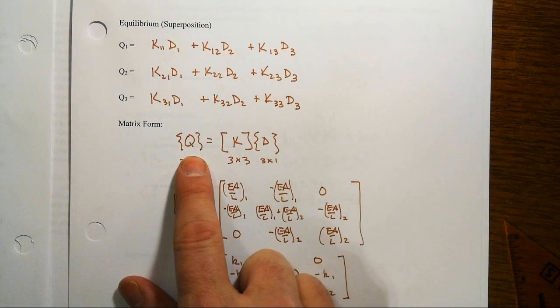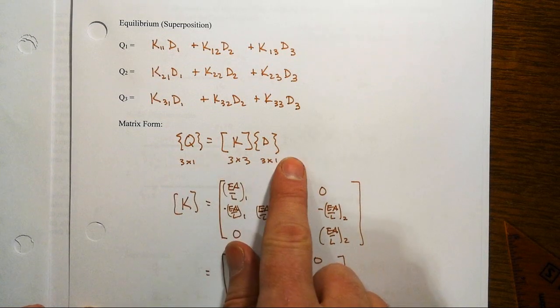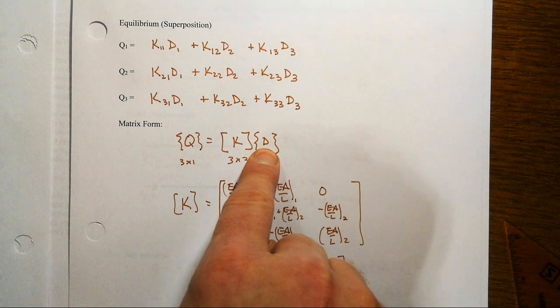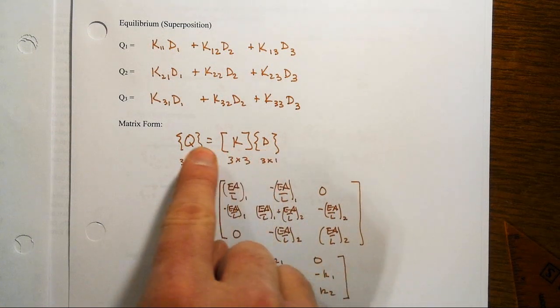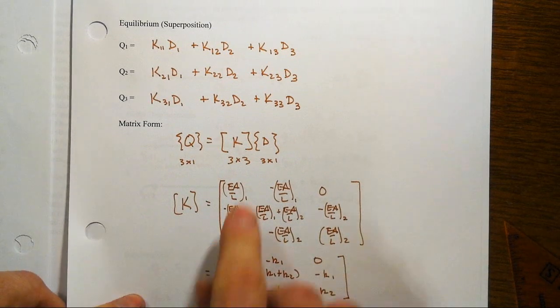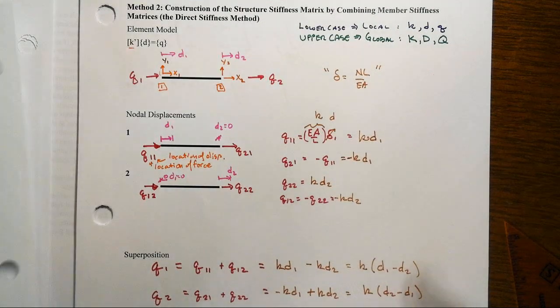Notice we ultimately end up with the same kind of expression here. These are just equilibrium equations where the unknowns are the displacements at the nodes, and we impose forces at the nodes. And so what are those displacements that are related to those imposed displacement pattern?